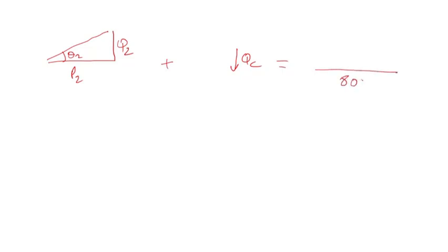And what I'm trying to do is, obviously I have theta 2, P2, Q2 here, and since the capacitor bank will have a negative reactive power, that's QC, so this plus this basically would equal the total active power of 800 kilowatt, and the initial Q2 is here, which is 705.53 kVAR.